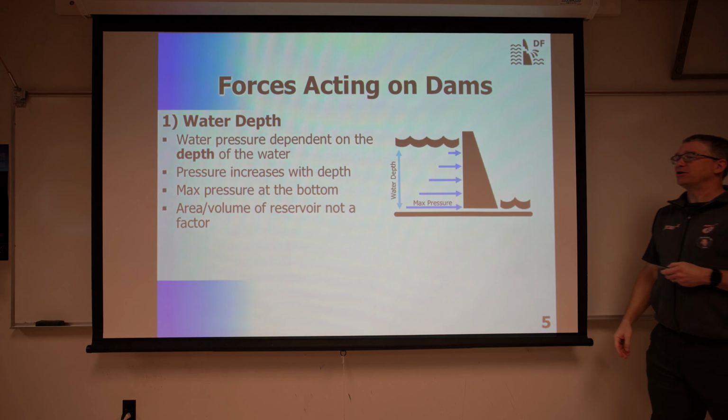The water uplift. This water that we have in the reservoir is under a tremendous amount of pressure. And not only is it pushing on the dam in this direction, it's also getting into the ground and coming up underneath the dam, creating what's called uplift. So in essence, the water is trying to push the dam this way, but also lift it up. Combine those, and really what the water is trying to do is tip the dam over, which is one of the reasons why dams are so wide at their base. Part of it is because that's the area of maximum pressure, but you also need a good foothold to resist that uplift movement as well.